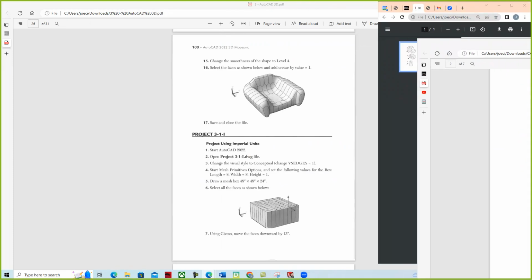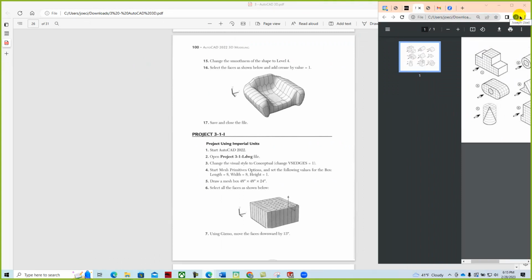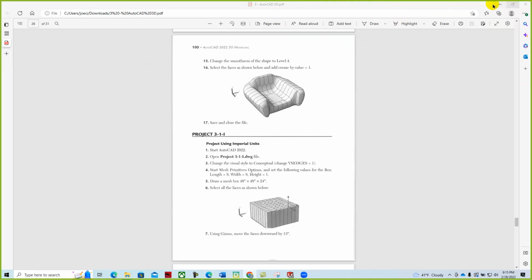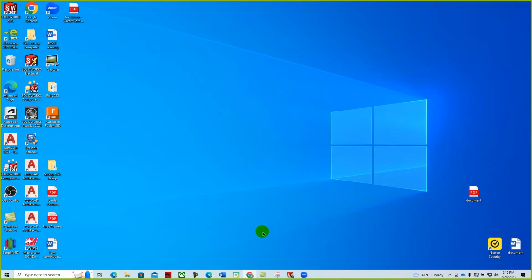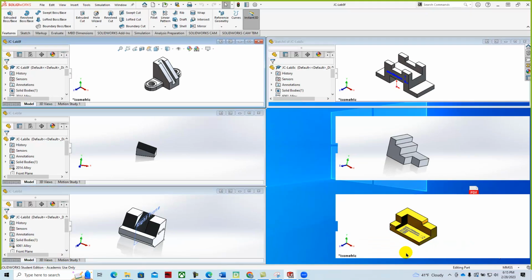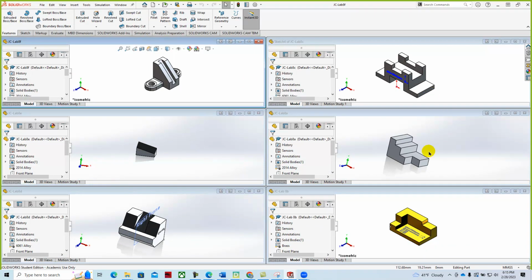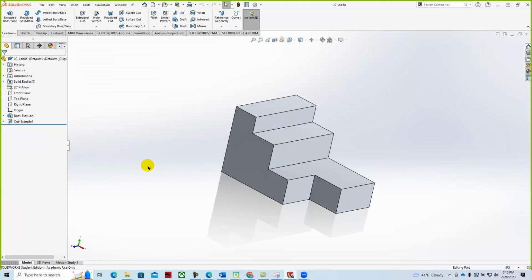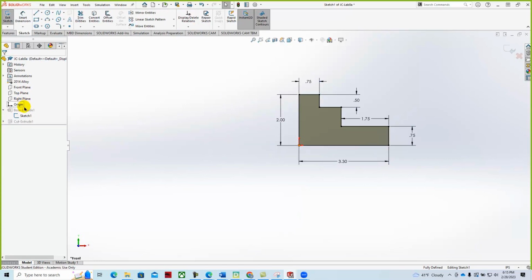As we go through and look at these, I've got a few other windows here. Let me just move them out of the way. AutoCAD, and we'll go into SolidWorks. We're working on these different models, and if we start with this first model right here, it's pretty straightforward. If we were to look at the sketch for it, I modeled it with the origin right here. Make sure that you set the units of measurement properly, so this one would be set for inch, pounds, and seconds.